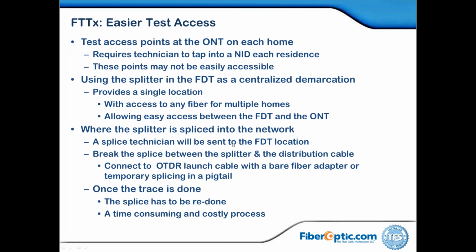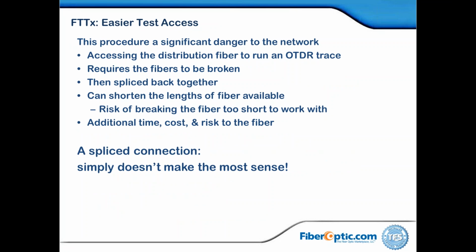Now, when things are spliced, as I mentioned just a little bit before, a high-level technician with splicing has to break it, test it, and then, as you see here, has to redo. So this is a very expensive way for the service provider to fire up subscribers, especially on a 1 and 2 basis. But it is about the connectorization. It's about easier test access. So I can access the distribution and run the OTDR as I just described. I might have to splice them back together, but plug and play, I could just plug them back in.